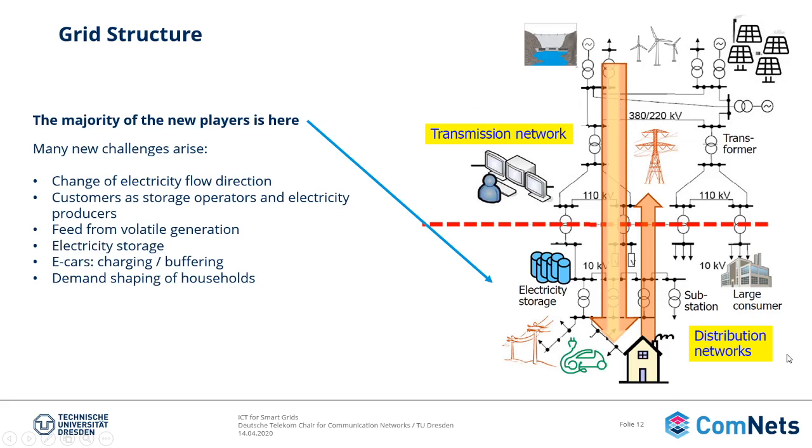However, in order to do so, you need to pass it through cables, and in these cables, there are a lot of losses. And in order to transport that through the cables with as low of loss as possible, you need to do transforming and use this high voltage, low voltage transformation in order to bring the voltage very high in order to avoid cable losses.